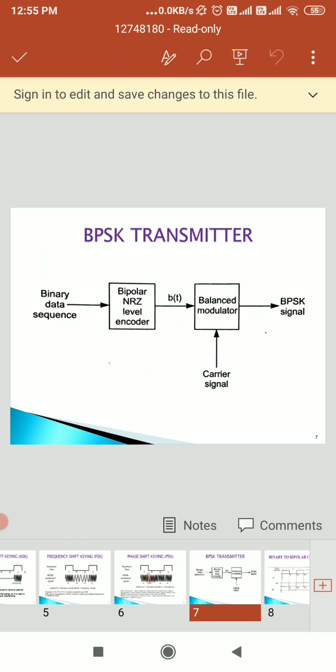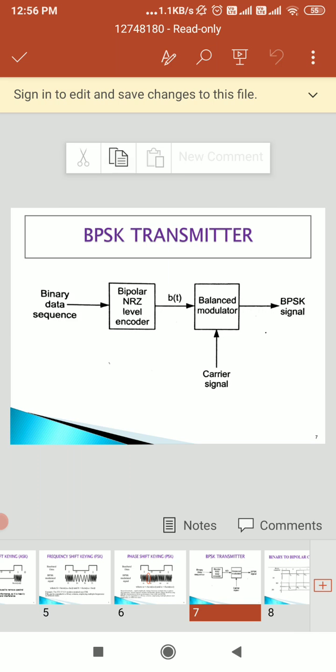So the system becomes very simple. But as it does not require the carrier to be recovered, the detection has poor quality, so the error performance of the system will degrade, and this method is called envelope detection. The modulation technique which employs non-coherent detection is called non-coherent modulation.